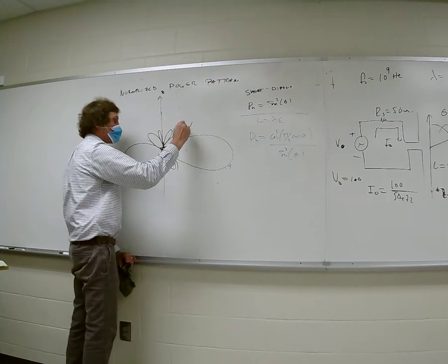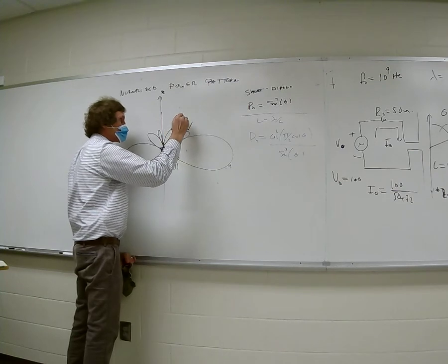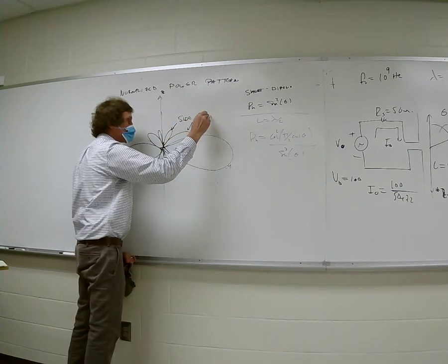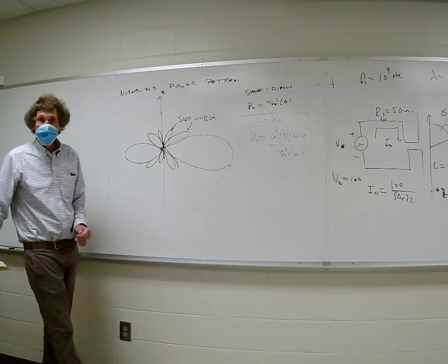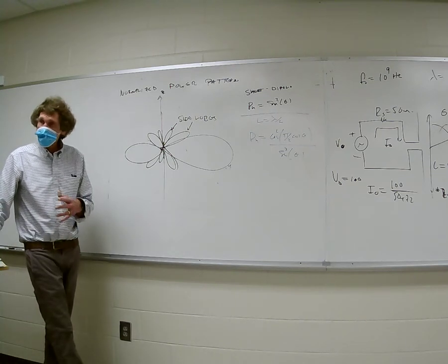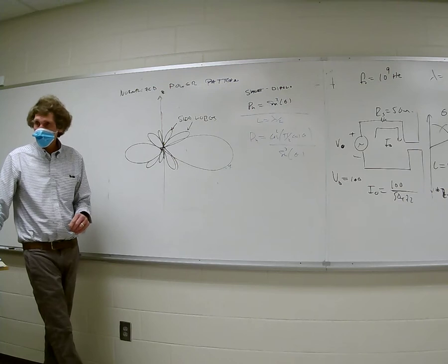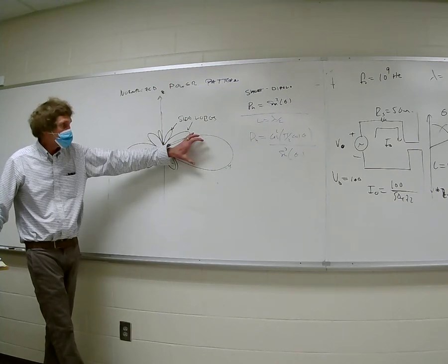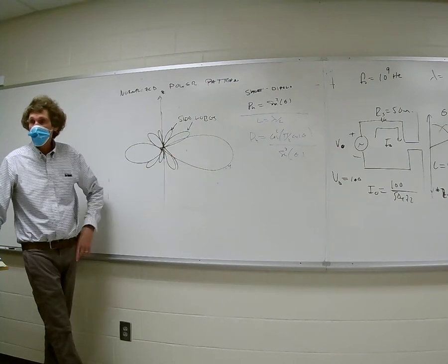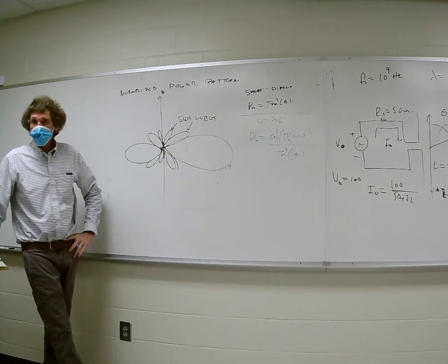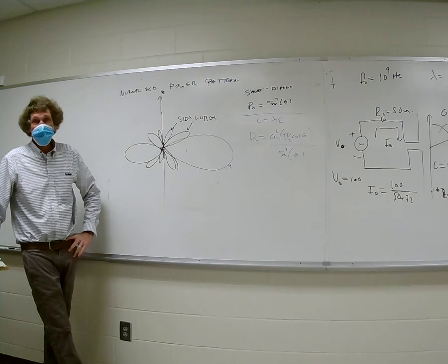All these are called side lobes. You don't want those. You'd like to get rid of them. And there's ways of suppressing or minimizing them, but it's always at the cost of causing the main beam to get a little wider. There's ways of doing this, and this is more advanced antenna theory. But you realize this: high gain antennas, it doesn't matter if it's a parabolic dish.